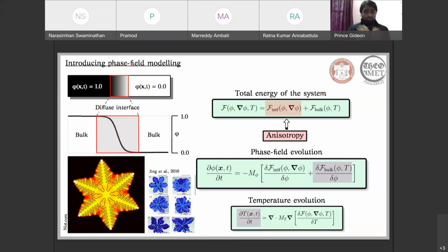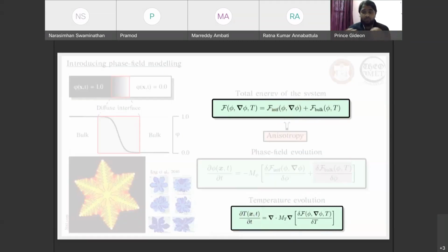Now, once we were able to address this particular question of modeling solidification with intricate structure, then the shift was to modeling similar structures or similar phase transformation in an isothermal system, wherein the driving force was largely governed by the concentration or the supersaturation of the concentration. So before proceeding in that direction, it was essential to observe the characteristic feature that was associated with the overall free energy density. If you look at the overall formulation of the free energy density, it is vital to note that the contribution of the bulk phase is sufficiently separated from the contribution of the interface. So you don't have any influence of temperature on the interface free energy density. So this is one of the features that renders thermodynamical significance to our phase field approach.